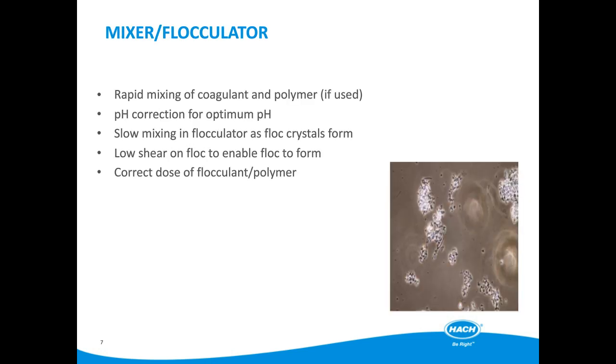Although the mixer and flocculator are often shown as separate tanks, this is probably only true for DAF used in potable water applications. For industrial applications, both of these parts of the process are in a serpentine section of inlet pipework, where flocculant and then later polymer are added. Mixing can be achieved without a motorized paddle by using a static mixer installed within the pipe.